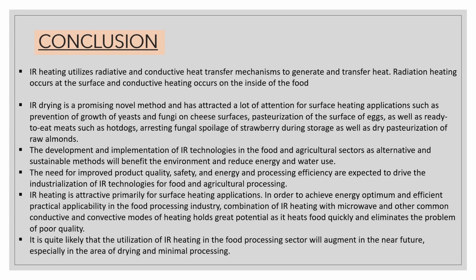Now, last but not the least, moving on to the conclusion. IR heating utilizes radiative and conductive heat transfer mechanisms to generate and transfer heat. Radiation heating occurs at the surface and conductive heating occurs on the inside of the food. Infrared drying is a promising novel method and has attracted a lot of attention for surface heating applications